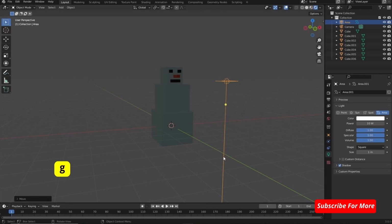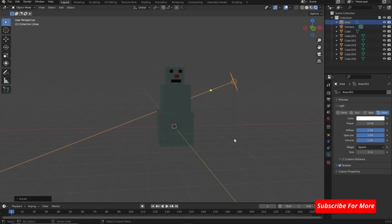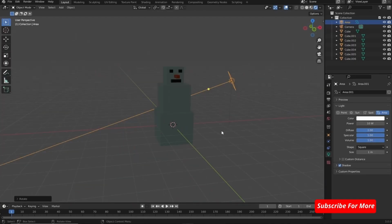And you can see this line, this direction on that side. We need to change this direction on this object. So to do that, press R on your keyboard for rotate and rotate it here. So you can see this line now changes from here to there. But if you move your 3D view, you cannot see any changes because this power is too small. So we need to give some power.